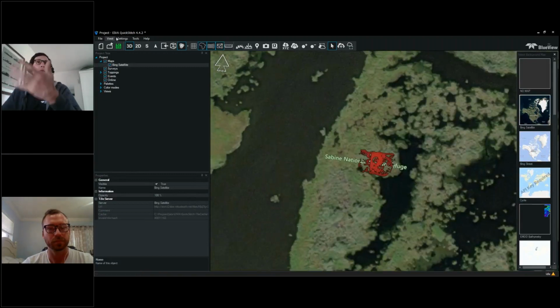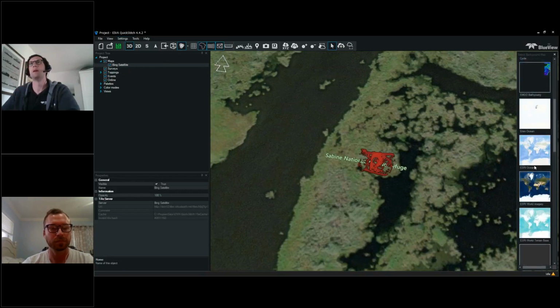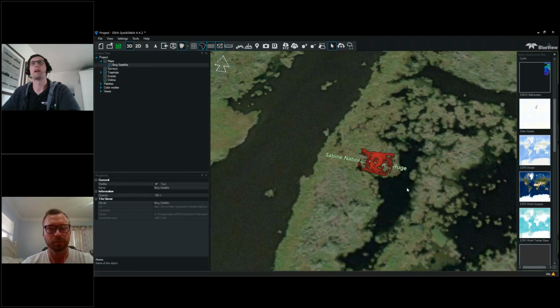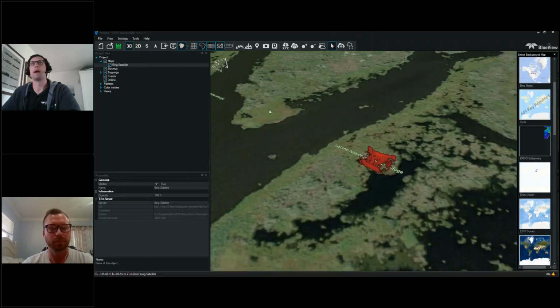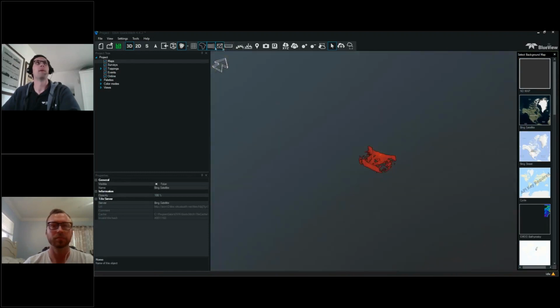And if you are in the correct coordinate system set up here in settings under geodesy, then it will overlay properly. So a number of maps here can make for a nice presentation. If you're doing screenshots or videos, it's nice to have data in the back here. So again, that does require an internet connection. For simplicity, I'm just going to do no map here.